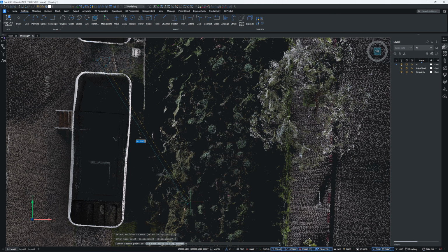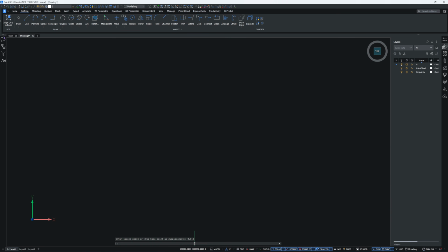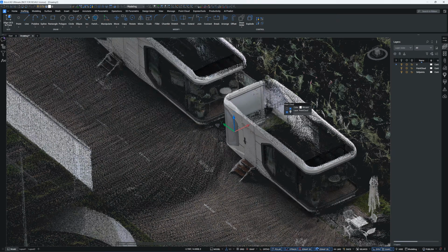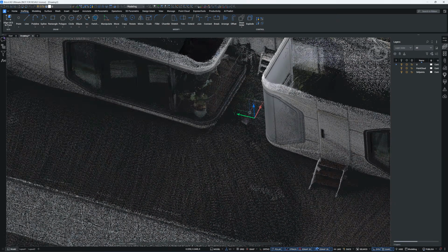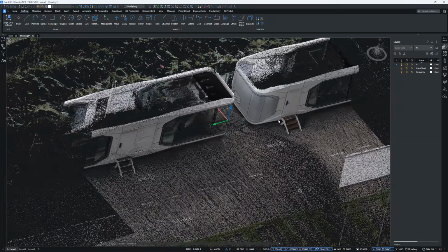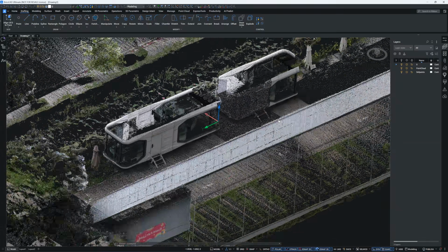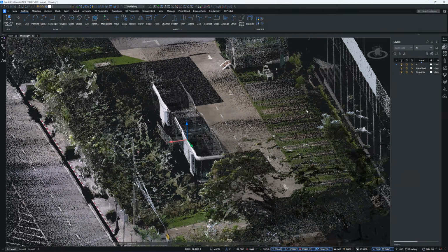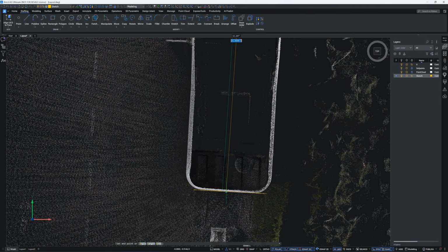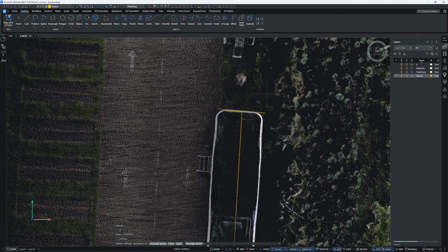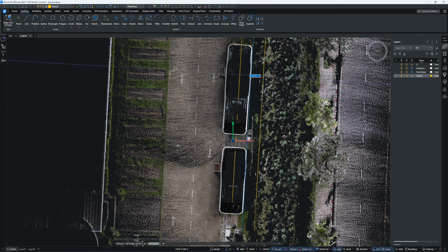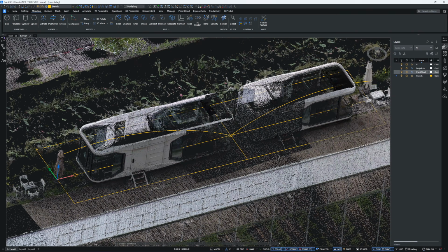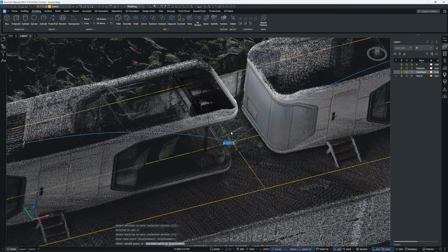I'm going to pick this point between the two capsule houses and move the point cloud to the origin. Since I'll be running a structural calculation later, it's better to work around the origin point, and I can always move the cloud back to its georeference position afterward. Here, I'm setting the canopy's center line and roof boundary. The east side will have a longer extension because the showroom building behind provides shade from the afternoon sun.